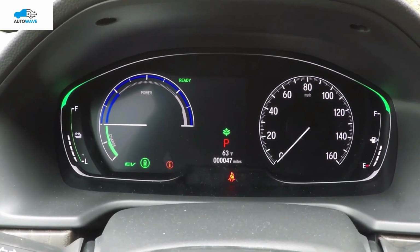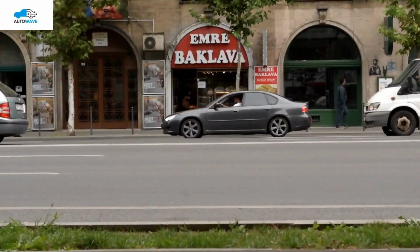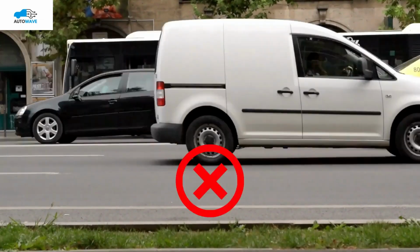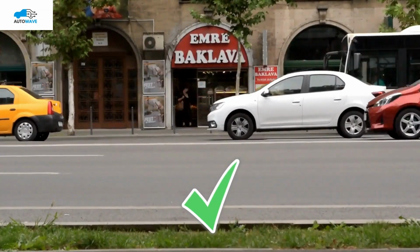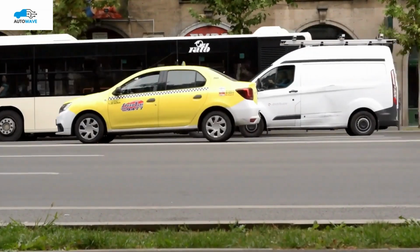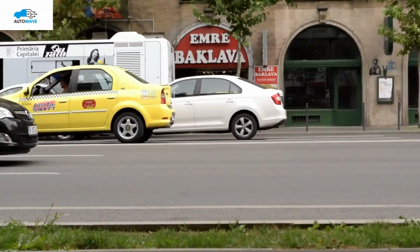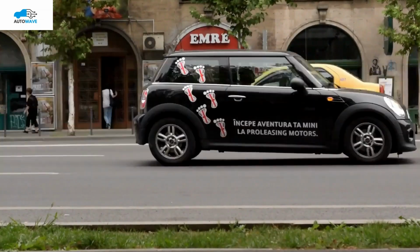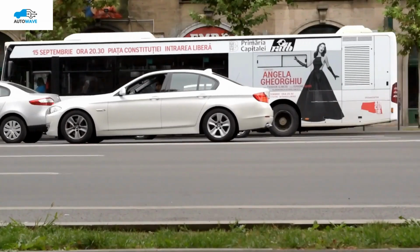Finally, the question is, when should you use Econ mode? The simple answer is, do not use it when you need high pickup. You can use it at a constant speed or normally in the city where high acceleration is not required. You should also avoid using Econ mode in very hot weather because it works on the air conditioning system and frequently trips the AC compressor.